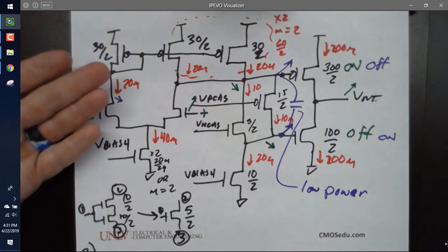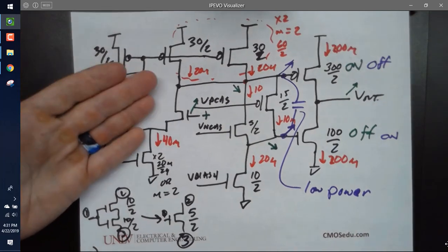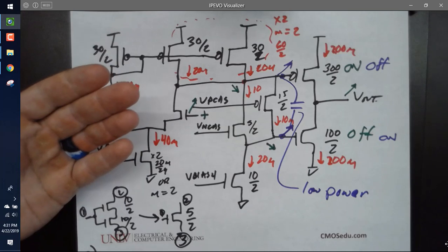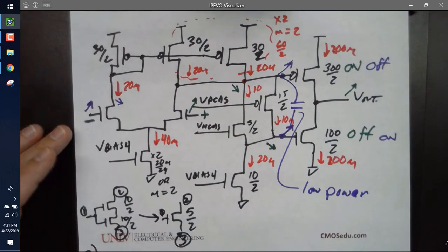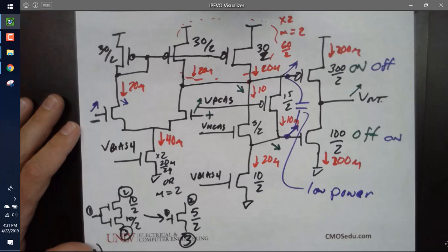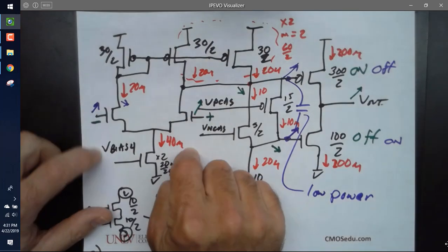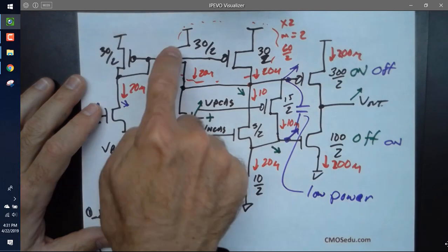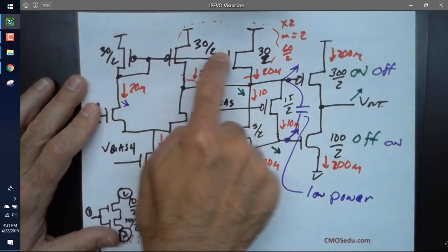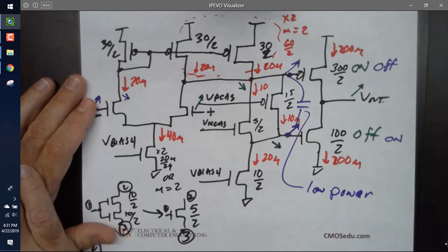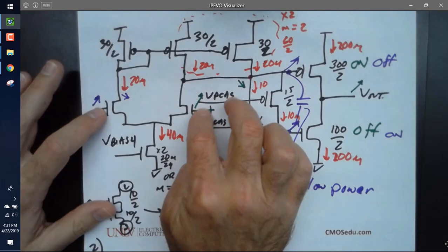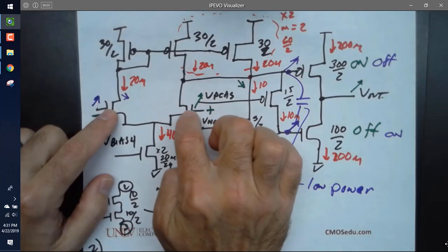And so you want to change the biasing, change the circuitry so you have a PMOS diff amp. And you have to be able to accommodate that because one issue we have here, if this goes too low, what happens to these transistors here and why? If I drive these down, what happens?